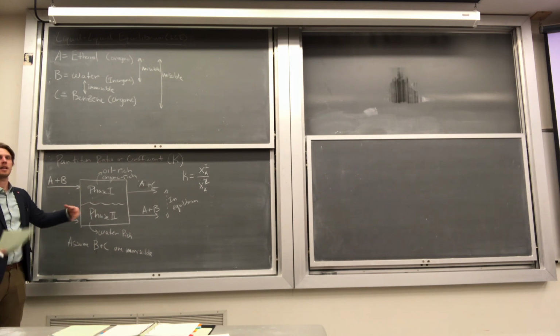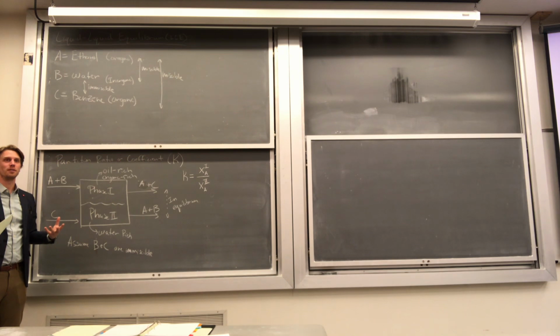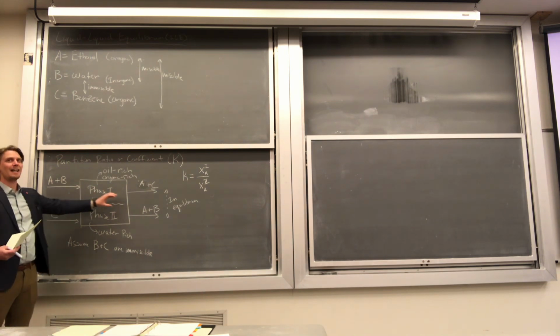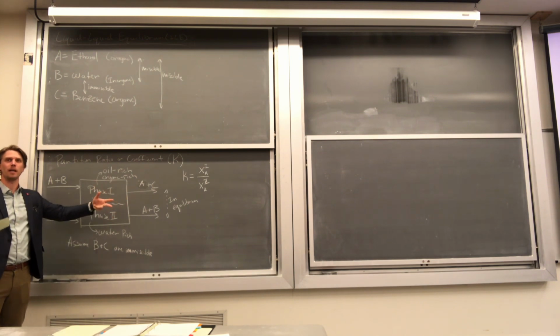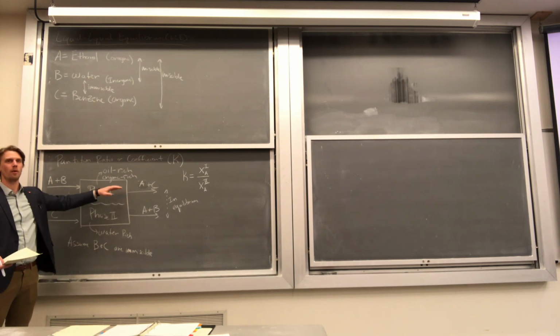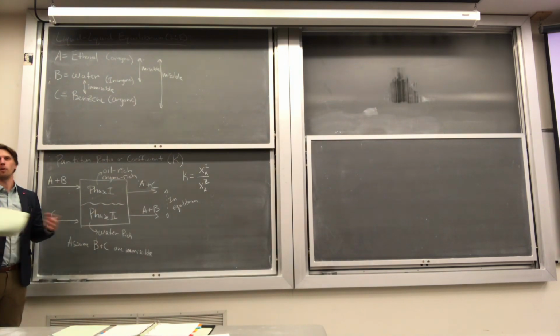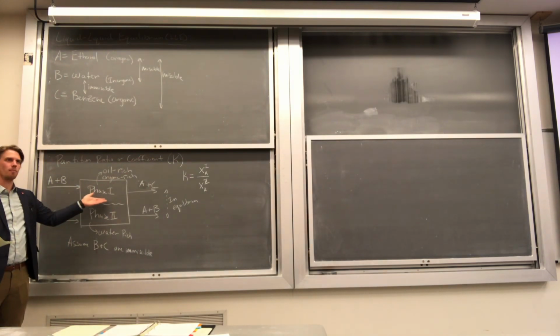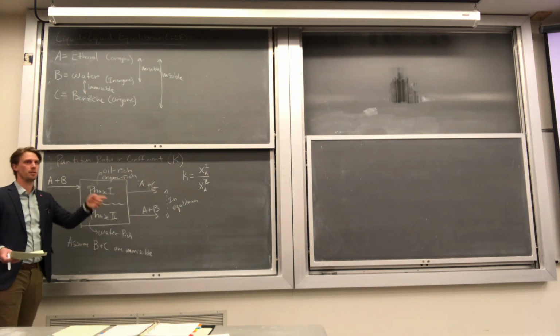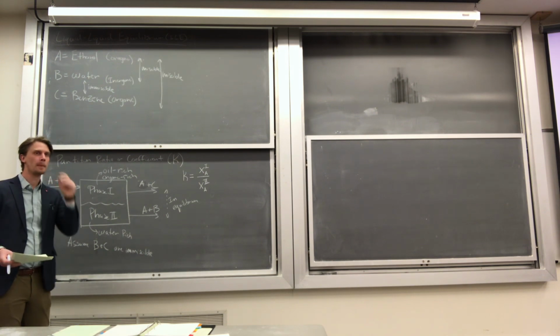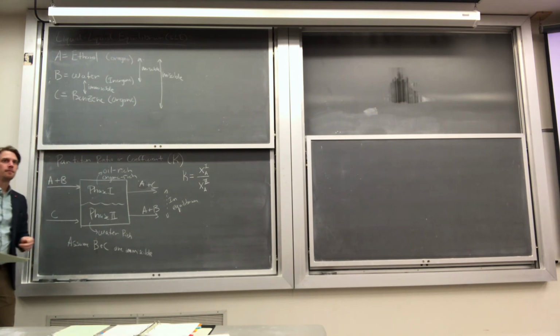The problem is sometimes oils have surfactants like soaps, and that can create emulsions. And then you get what they call a rag layer of this emulsified oil and water mixture that they have to add chemicals to break up. Otherwise, you'll get water in the oil phase and oil in the water phase, and no one's happy. Because then you have an environmental cleanup issue, and you also have basically exploding water in your refinery because you heat these up to a couple hundred degrees. Yes? You were saying that the oil can have soap that causes emulsification, like natural soap? Yes, surfactants. Yep.